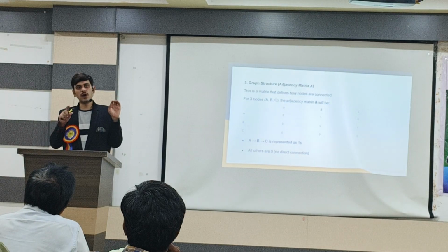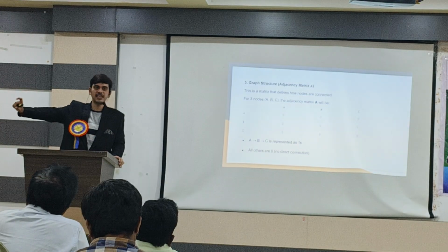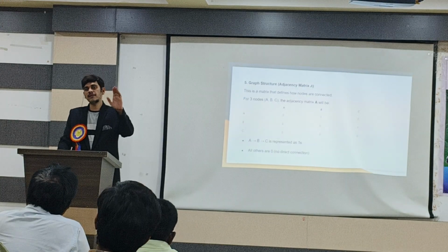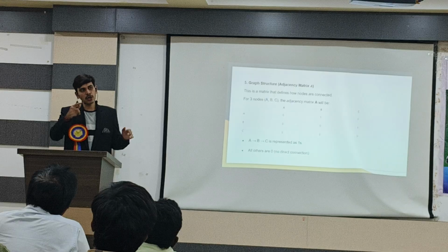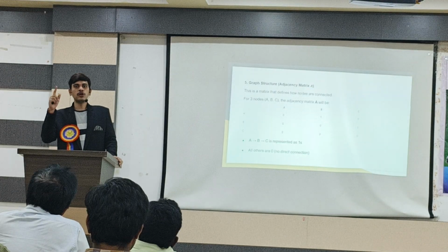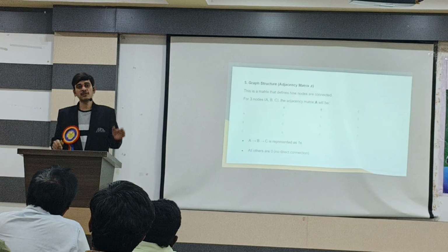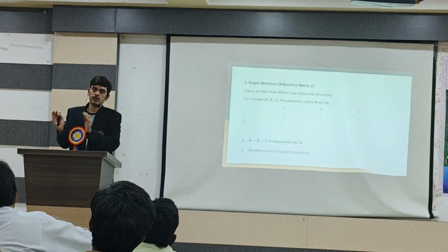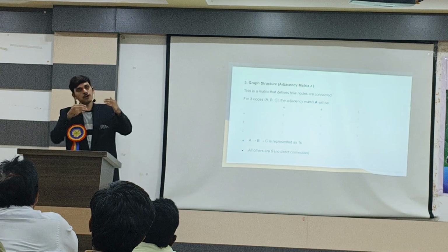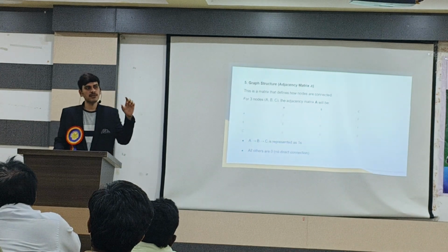First, how we fix this: data path optimization. First, we have to optimize everything in the data path, and only then go to the clock, because the clock is very sensitive, right? The clock goes to many modules, so it can cause a few issues. So first we try to optimize all those things. To get the optimal layout, from the initial stage of the project we have to get the constraints proper.